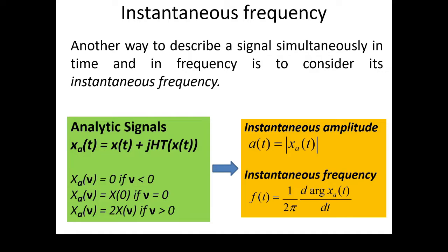Before this STFT came into existence, there was a concept called instantaneous frequency and group delay. Let us first talk about the instantaneous frequency. As the name suggests, at a particular instant, what is the frequency we want to find out. For getting the instantaneous frequency, and even some of the strong tools of joint time frequency analysis, we have to convert the signals to analytic signals, and then we can apply those advanced tools.